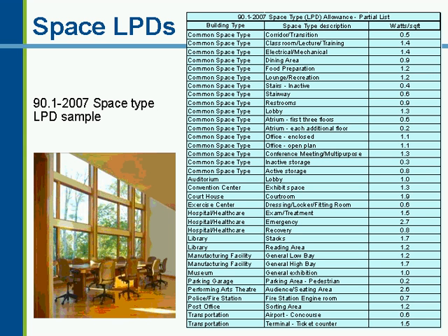There are a little over 100 different space types in the standard, so you do have quite a bit of flexibility. You'll see at the top some common space types. These will be found in lots of different buildings, the same value whether you use it in an office or a restaurant, for example. Then you'll get down to specific building type spaces. And for example, there are 3 hospital healthcare items in there for 3 different space types: exam, treatment, emergency recovery. There are even more hospital healthcare categories, but we just provided 3 here. You'll notice that the lighting power densities are different for each of those because the lighting requirements are different. They range anywhere from a very low 0.8 up to 2.7, depending on the application.